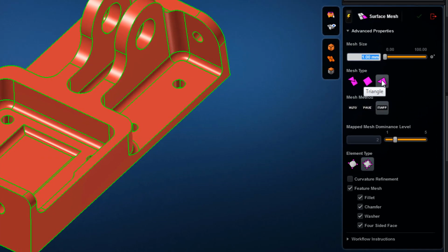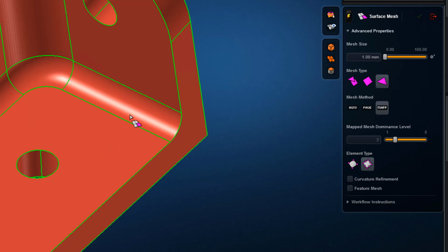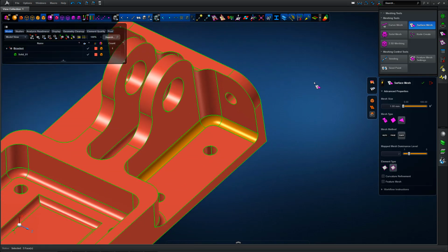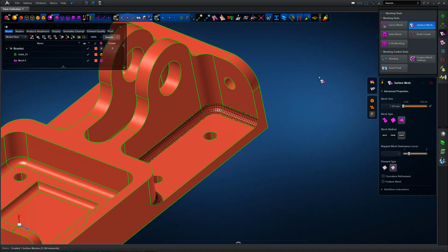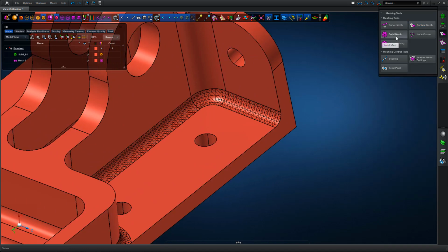So some different techniques now where we can look at refining the mesh in areas of interest. What we're going to do first of all is surface mesh some faces of the solid using the standard surface tools, in this case the fillets shown highlighted in this selection. We can pick those regions, middle mouse to accept, and we've got a 1mm element edge length in these regions.